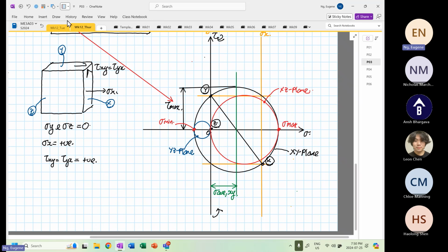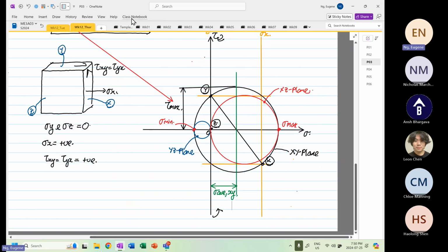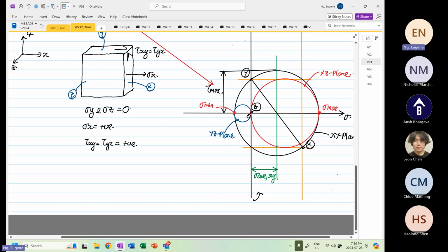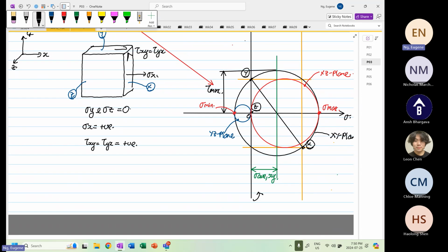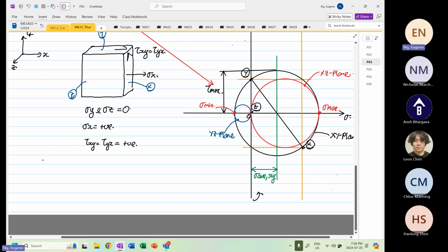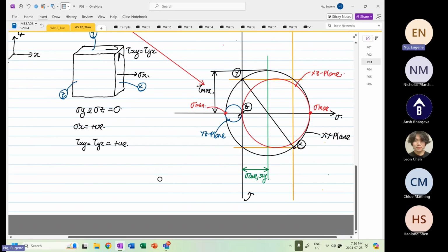So now if we have to formulate our stress XY, okay, so we are going to calculate our stress average. Let me see, look at space. Yeah, I think we're okay. So we have stress average XY is equal to stress x plus stress y divided by 2, right?